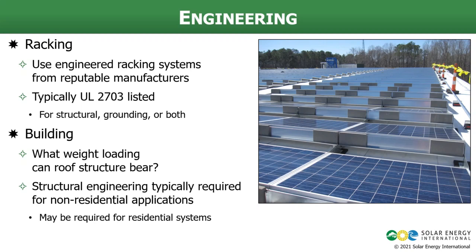Historically, residential systems did not need structural engineering, but that is changing over the last few years. A lot of jurisdictions are requiring not necessarily a stamped plan set for residential designs, but a lot of them are starting to require a letter from a professional engineer saying that the building will support the load of the array.